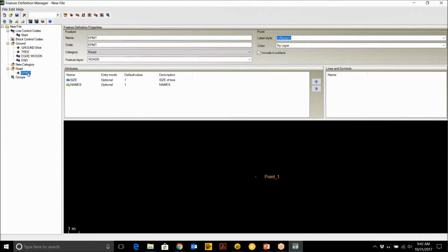From someone that has used field to finish in the past, I would recommend that you start maybe slowly, maybe just start with some break lines, tops and bottoms of banks, maybe just some edge of pavements, and continue working up. I found that the first project I did with this process, if I started and tried to draft the entire project right away, it was a little overwhelming. So I started a little slower by maybe just doing some simpler features, and it all saves time in the end, and you create a better deliverable because the person that was in the field knows exactly how it looked, and they can QA/QC that, if you will, on your data collector before it even hits the drafter's desk.